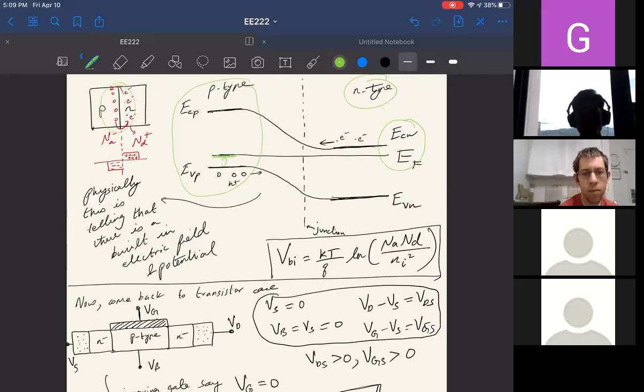And so because of that, the band actually starts bending, which you see here. I mentioned earlier that the conduction and valence bands are very sensitive to where they are with respect to the Fermi energy, right? So because the band bends here, and because of the exponential dependence, this region is going to be completely depleted of charge carriers. This region where the band bends does not have any free electrons or holes, and it is called a depletion region. It's completely devoid of any free carriers, okay?